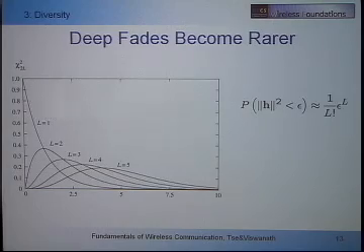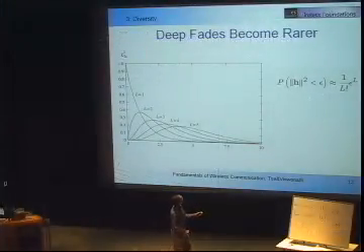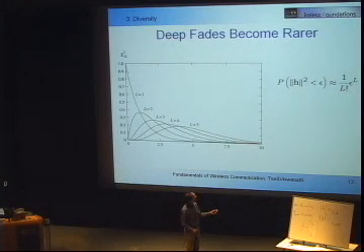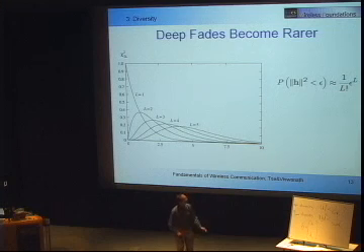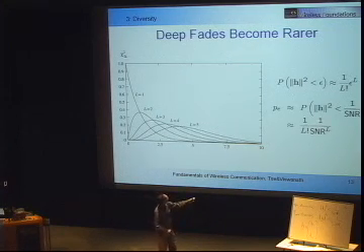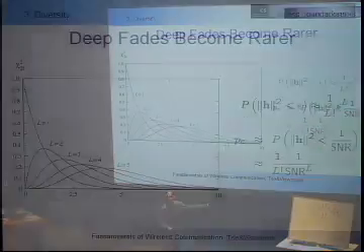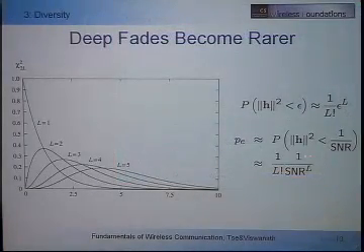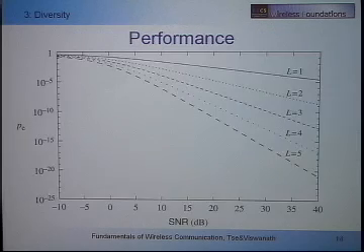Okay, in fact, one can estimate this probability is proportional to 1 over L factorial, epsilon to the power L, where epsilon is a small number. So you can think of epsilon as precisely equal to 1 over SNR in this problem. So this error probability is like 1 over L factorial, times 1 over SNR to the power L.